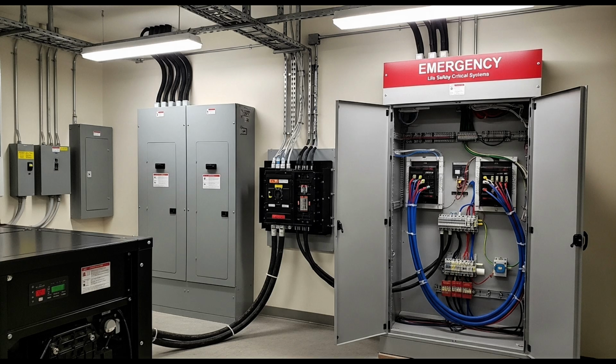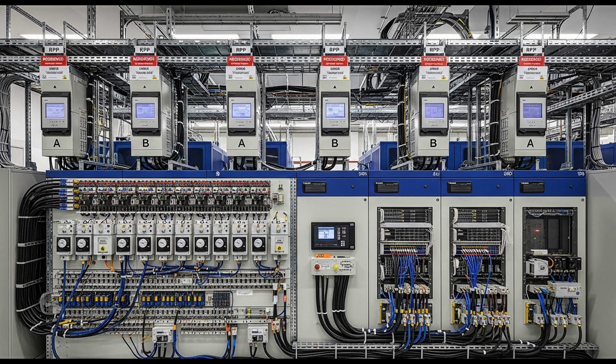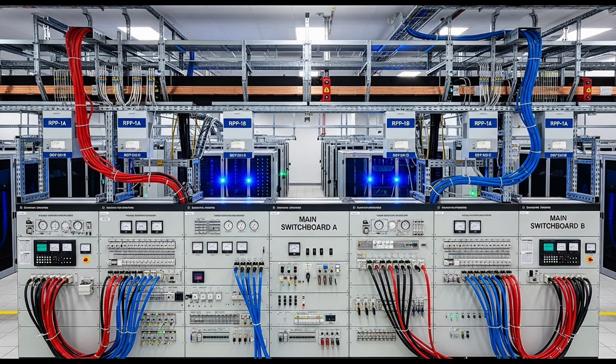These double-pole breakers connect to both hot bus bars simultaneously, capturing the full 240 volts between them. The appliance uses both hot wires and often doesn't even need a neutral connection, since the load is balanced between the two phases. The grounding system operates somewhat differently.